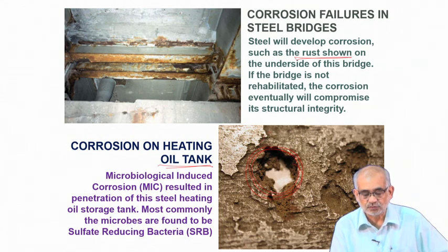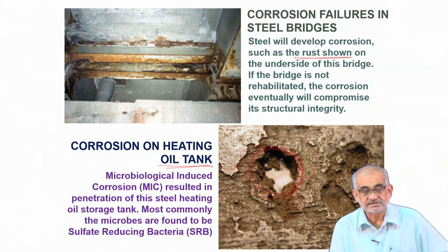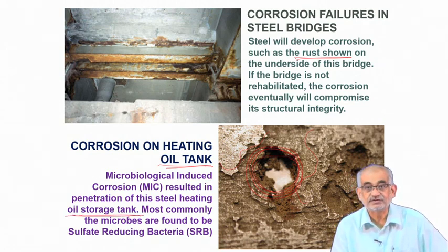And if the coating or the protection is peeled off, and the fresh metal is exposed, then these bacteria can come and gradually grow. It can be not just bacteria, it can be algae or fungi or various other microorganisms which for some reason manage to peg to some corners or crevices. And if that happens, they gradually multiply, they grow, and when they grow they start feeding on the metal. So they penetrate and they can create such a huge hole, and once such a hole forms, then obviously this oil storage tank is no good anymore.